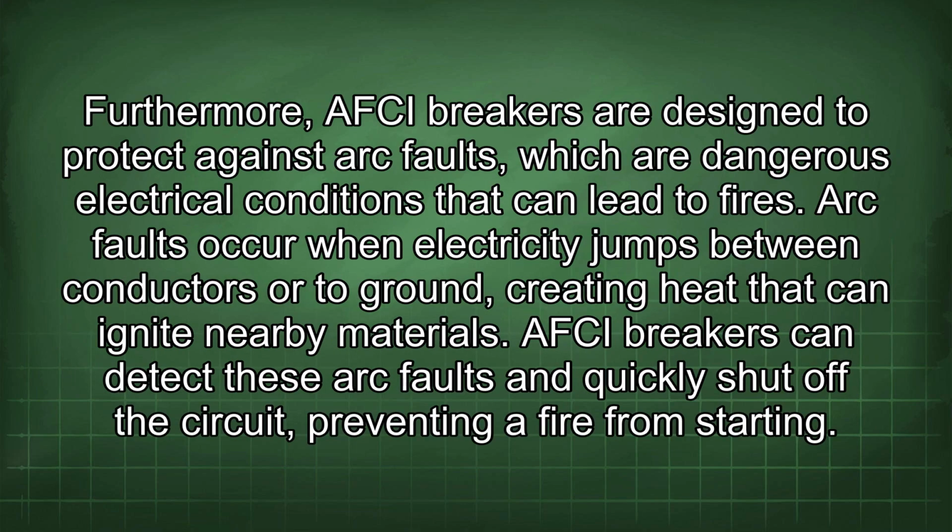Furthermore, AFCI breakers are designed to protect against arc faults, which are dangerous electrical conditions that can lead to fires. Arc faults occur when electricity jumps between conductors or to ground, creating heat that can ignite nearby materials. AFCI breakers can detect these arc faults and quickly shut off the circuit, preventing a fire from starting.